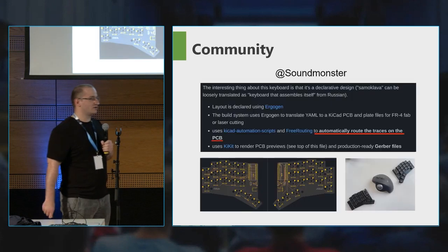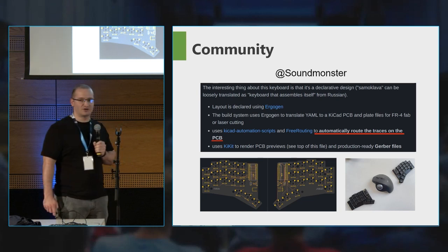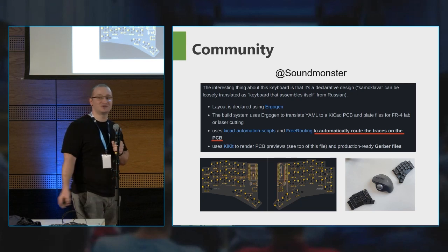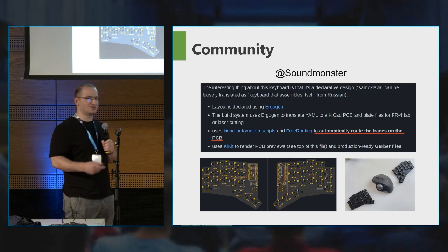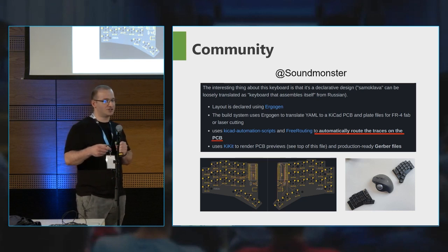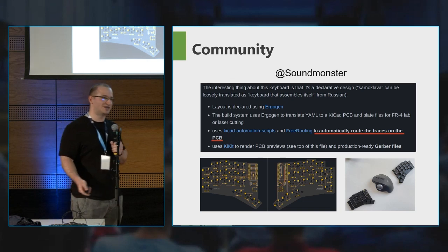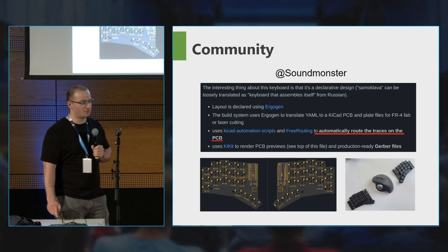And also giving us a glimpse into the future is Soundmonster, whose Samaklova repository even bridged the last remaining human interaction bit, because it just defined a fully automatic GitHub workflow that runs Ergogen and then runs the resulting PCB through an auto router, a topological auto router that actually outputs a fully complete PCB for manufacturing.